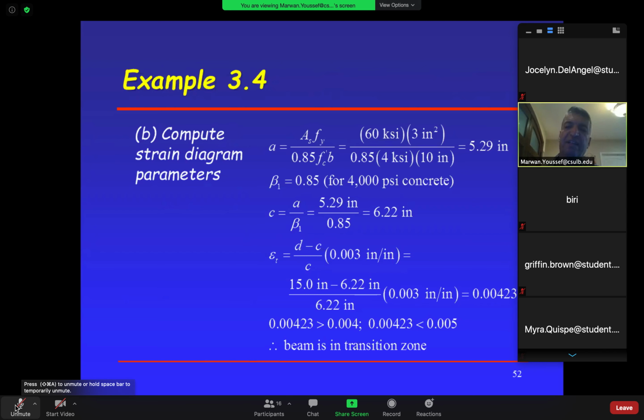So you have to retrofit it if the city or the government agency asks you to do that. In theory, the beam is deficient, right? It could be deficient by today's code, by the way, but it was built in the 1960s, and at that time it met the code. So that could be the case too, and the city can say, you know what, we're going to grandfather you in. You don't have to retrofit that. So there's a lot of things. It depends on the governing agencies. Does that make sense? That makes sense. Thank you. You're welcome. But good question.